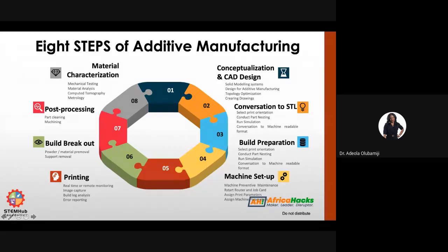So design is not done when you finish designing your part. When you want to print the part, you need to redesign it for additive manufacturing, considering all the tolerances and all the different boundary conditions that 3D printing has. Because if you don't, that part will be too stressful. You may not be able to print it. So I wanted to share that.